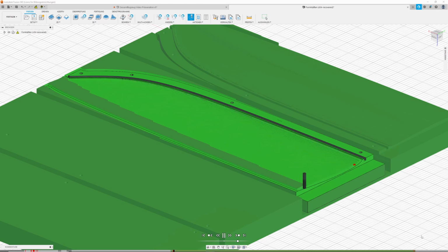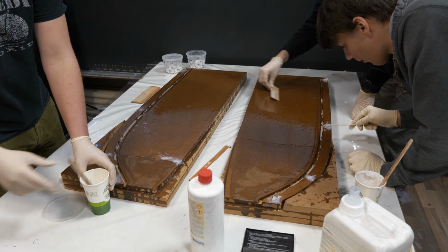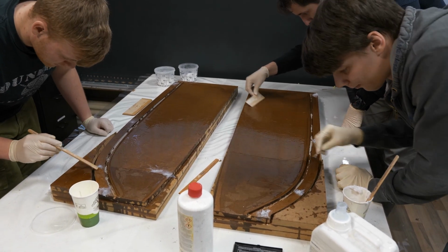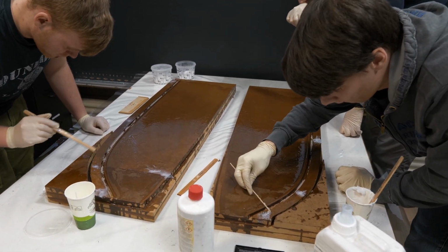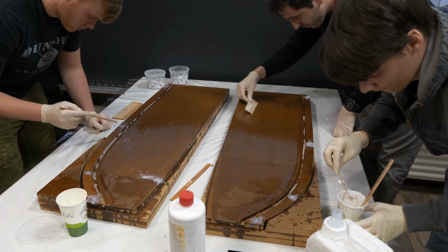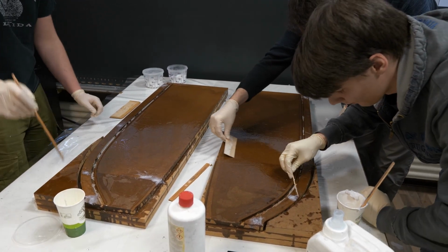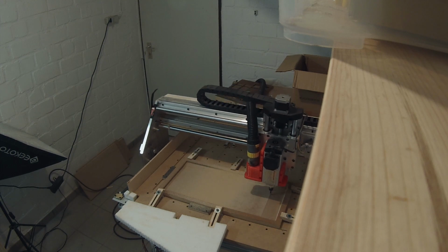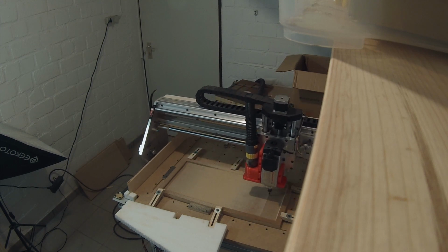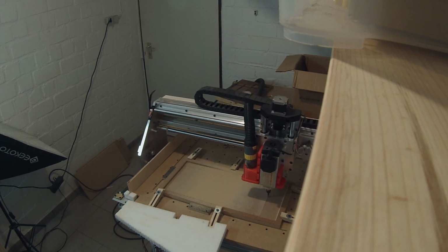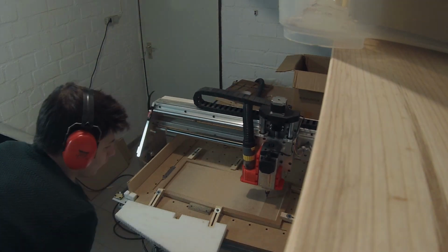We decided to use MDF for the molds. It can easily be machined, but it's too soft to be used as a mold as it is. To strengthen its surface, we soaked it in epoxy resin. The cured epoxy resin makes a very hard surface, which we could now machine to its final dimension and then polish. Another advantage of this method is that mistakes can easily be repaired and the mold blank can be reused